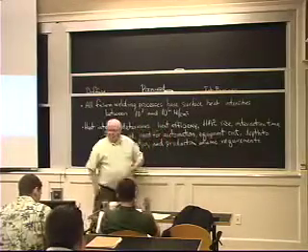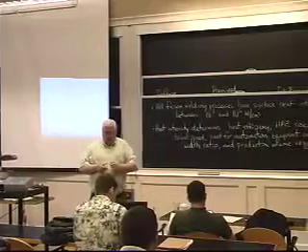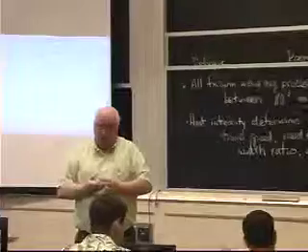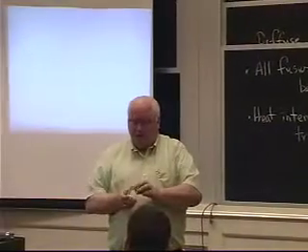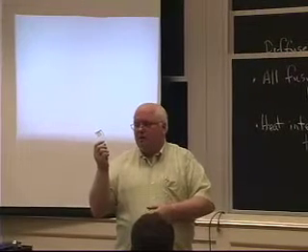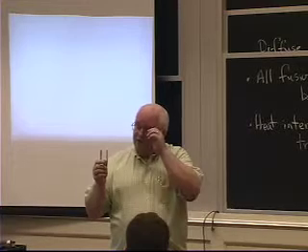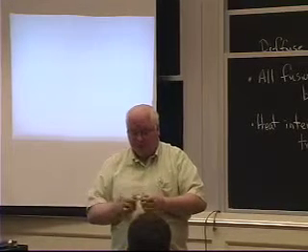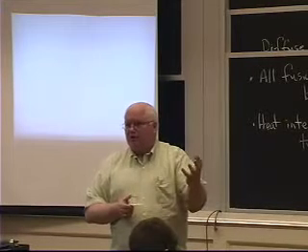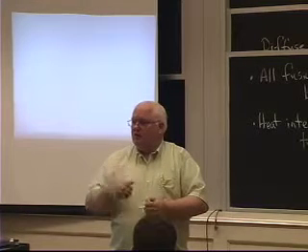Depth to width ratio, one of the handouts I didn't show you last time. This is actually a sample that Hitachi gave me over 20 years ago, but they had a 5 kilowatt laser they had developed, and the first one they actually show you, this is actually a piece of, is it lucite? Yeah, lucite. Polymethyl methacrylate. I know the chemical name. Anyway, it's just a piece of plastic, and if you hit it with the laser, you actually vaporize the surface of the plastic, and this is one of the ways they figure out whether you've got a well-shaped beam.